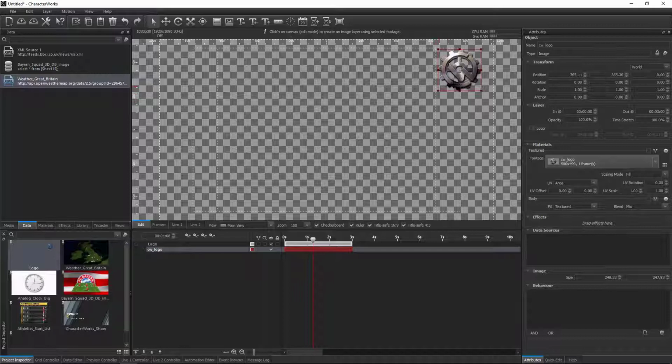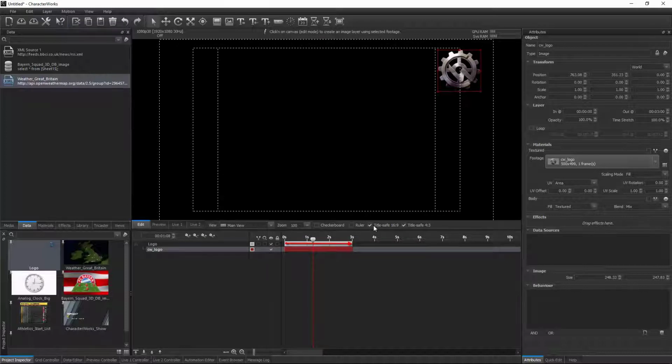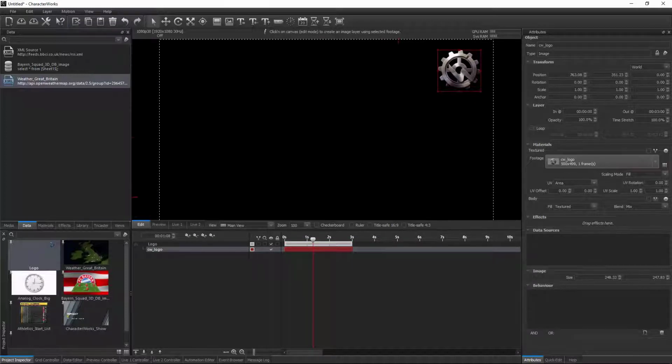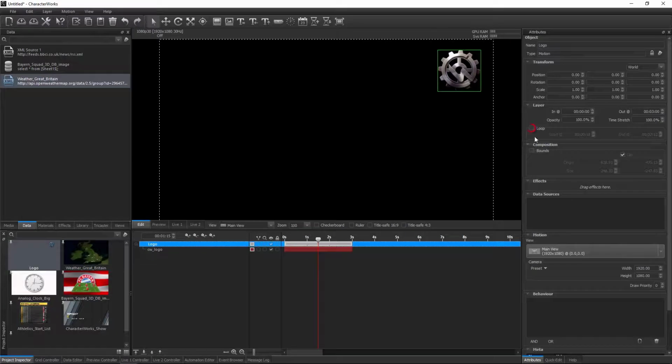By default, the motion occupies a duration of 3 seconds on the timeline, and as such, it will disappear after 3 seconds of playback. To make the motion remain on screen for an indefinite amount of time, enable its loop via the attribute editor and set the in and out points for the loop. When the motion is started, playback will proceed as usual.